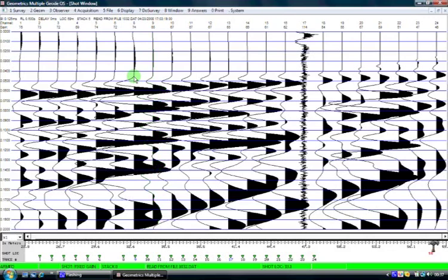It's important with seismic refraction that you do examine the data closely in the field, because it's absolutely critical that you're able to identify where these first arrival points are, or first breaks if you like, because quite often what looks like good data when you're in the field, when you come back to the office to try and edit the data and process it to interpret it, these first arrivals may not seem very sharp, but by then it's too late.